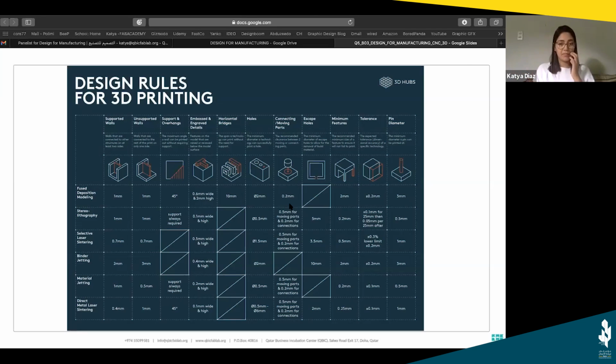And even by making it 0.2 mm smaller, it will be really tight. So I recommend you play with your printer and see your own parameters. If you don't have a printer and you're going somewhere, then yes, use 0.2 mm less for parts that will go inside another or moving parts. If it's a part that does not need to be attached and it will be moving, I would even increase it a bit more.